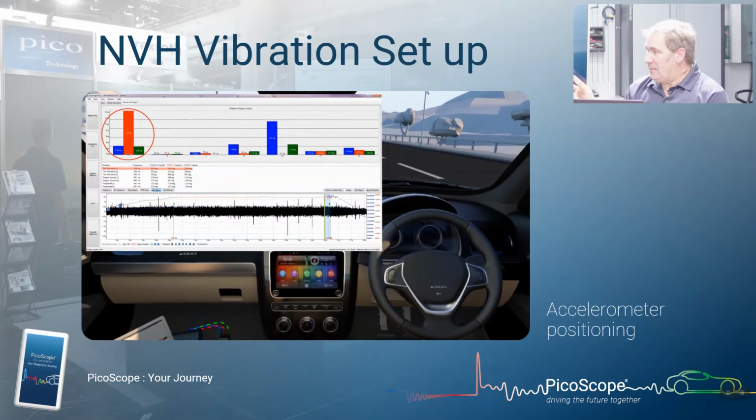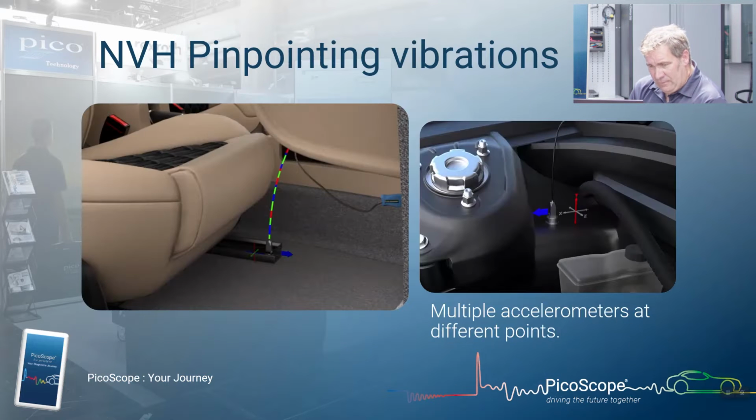The animation runs quite quickly as well, so you'll notice, Steve's already mentioned it, when we're positioning that accelerometer down, we want to make sure that screw thread is pointing forward, because you have to have it the same every time you set up. It's really, really important. And again, we're going to do this live on the vehicle in a little while, so you'll see that actually live. And I've just pulled out a couple of examples here.